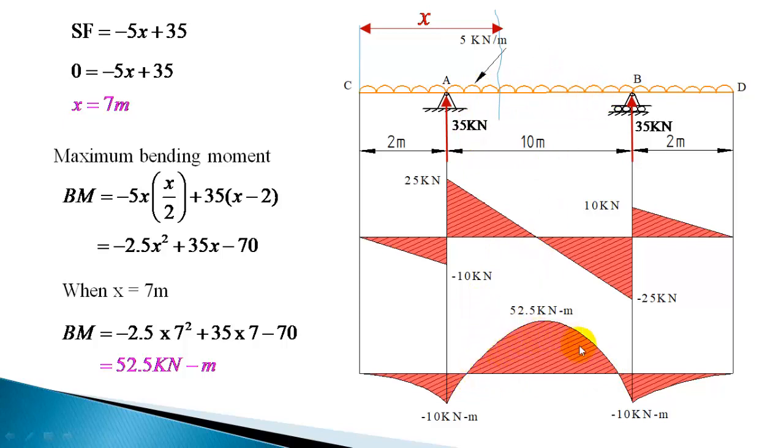So this is a bending moment curve, and bending moment is coming to 0 here. These 2 points, bending moment is coming to 0. So you have already written the bending moment equation. And bending moment equation can be used to calculate bending moment if you substitute x, or if you know the bending moment, you can solve for x. So here we know the bending moment. Bending moment is 0 at these points. Okay. You can calculate these points, that is points of contraflexure, by substituting bending moment as 0.